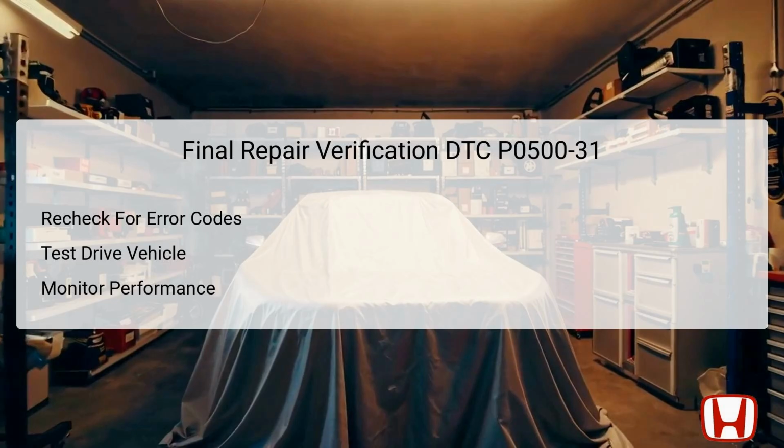After completing the necessary repairs, recheck for any Diagnostic Trouble Codes, DTCs, and confirm that DTC P0500-31 has been cleared. Next, conduct a test drive to monitor the vehicle's behavior under various conditions, ensuring that it accelerates smoothly and shifts properly. Observing the performance during the test drive will confirm whether all systems are functioning appropriately and whether the repairs have resolved the underlying issues. If no faults are detected, you can conclude that the repairs were successful.